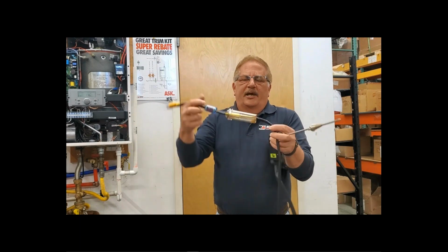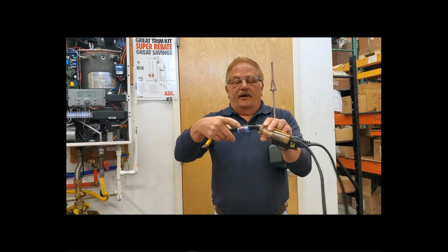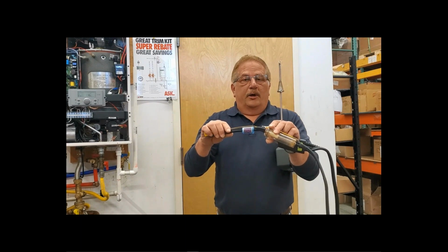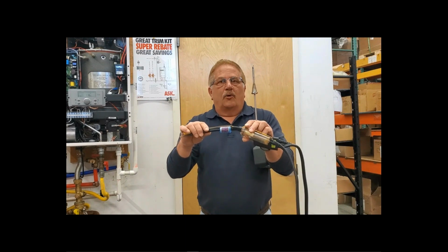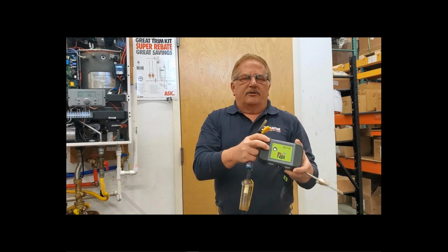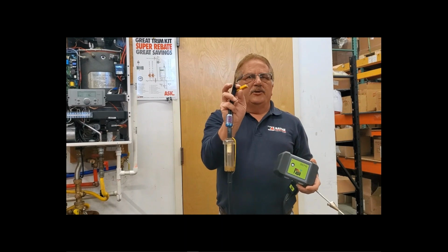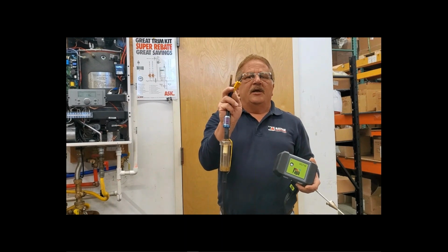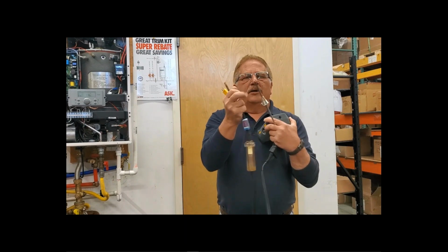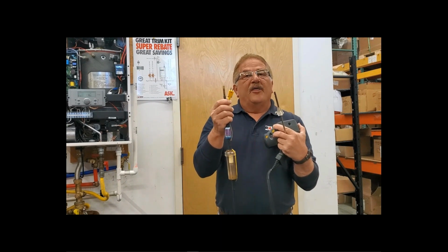Our sample probe also has a condensate or water trap filter, and I also have a carbon filter on there. That carbon filter would be utilized for oil work when you're doing the combustion analysis on oil burners and oil boilers. The end of this probe has an electrical connection. Next to that electrical connection is also a tubing connection. That tubing connection is where those combustion samples are coming in from. The electrical connection is for temperature. You can actually think of this as nothing more than a glorified thermometer.